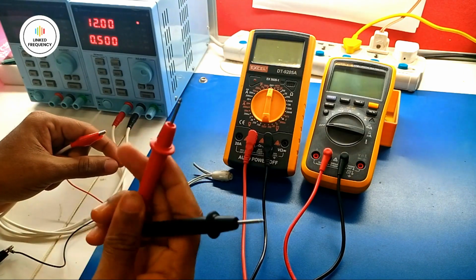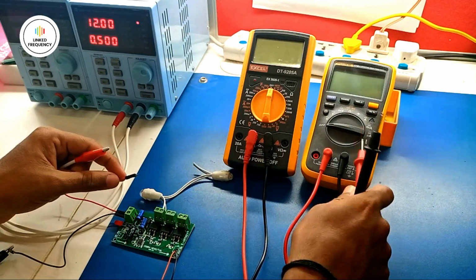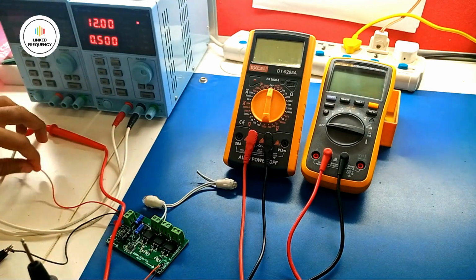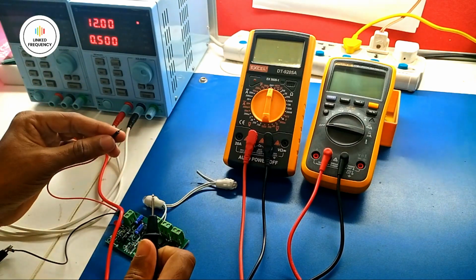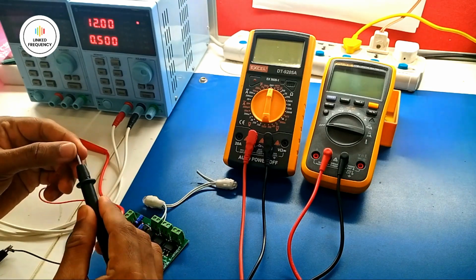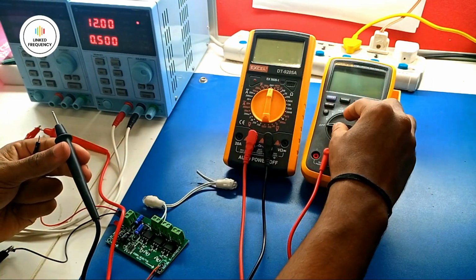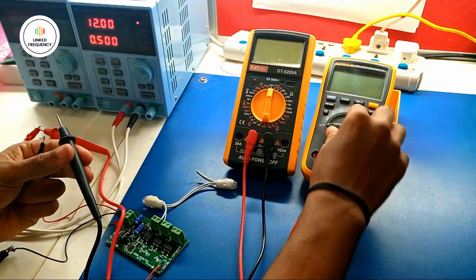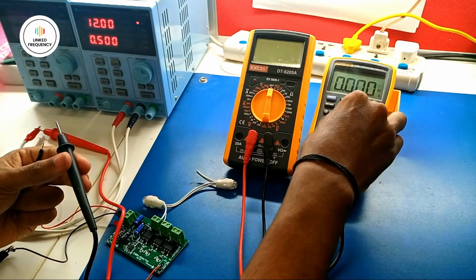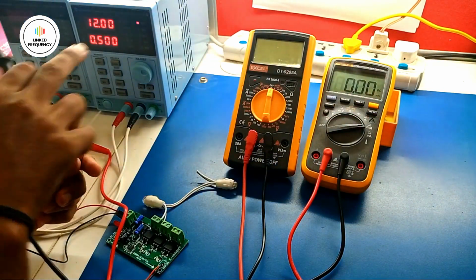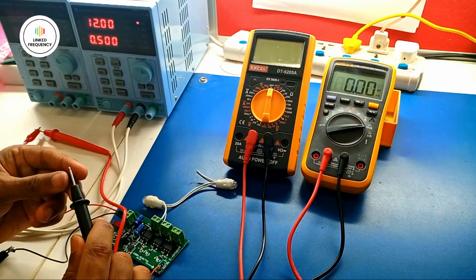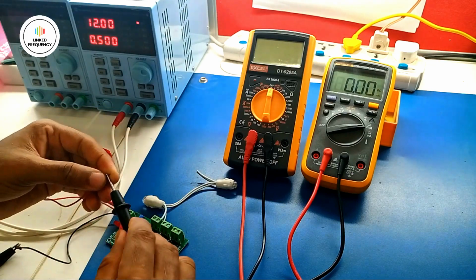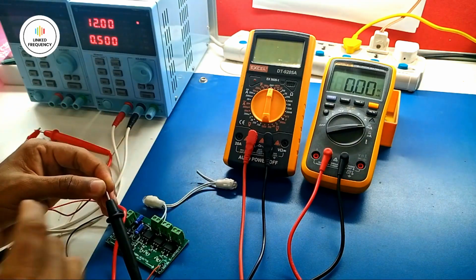I'll connect the positive probe of the digital multimeter, I'm using a Fluke multimeter right now, to the power supply directly. And then I will connect the positive input pin of the circuit to the negative probe of the digital multimeter. And of course, I have to set this digital multimeter to milliampere before turning on the power supply. So I'll set it to milliampere first. Do remember, before turning on the power supply, you have to set it to milliampere, and then I'll connect it like this. Holding this like this is not good, but right now I do not have any resources to hold it properly, so I'm just holding it by hand.